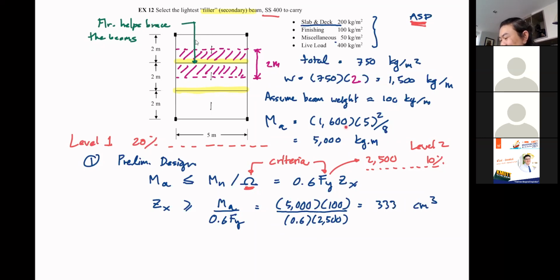The steel is like 5% of the weight, but the weight of the concrete beam could be as much as 30-40% of the entire load that you are designing for. In other words, the concrete beam will have to support itself before anything, right? Because I was doing steel so much, I forgot to include the self weight for concrete. So that's kind of not nice.